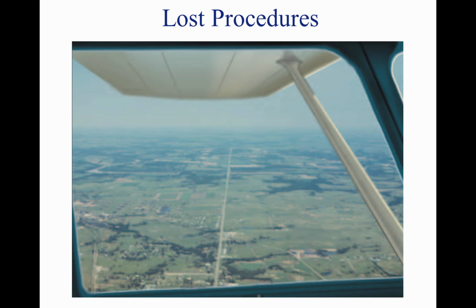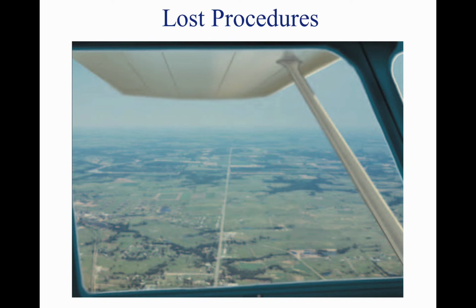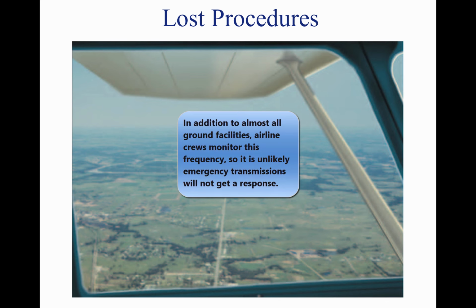If the situation becomes threatening, transmit the situation on the emergency frequency 121.5 MHz and set the transponder to 7700. Most facilities and even airliners monitor the emergency frequency.